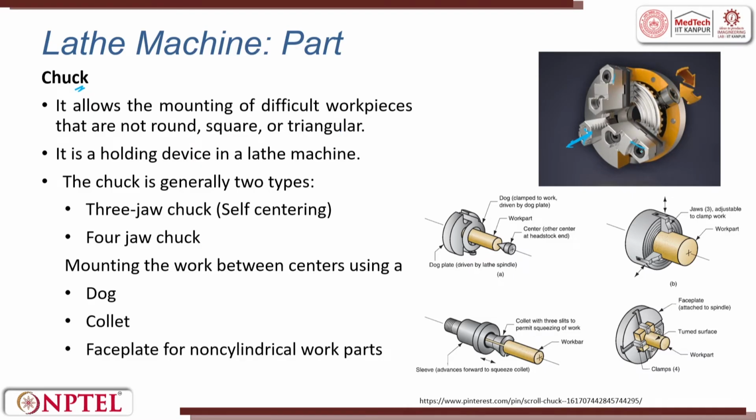The 3 jaw chuck we are talking about is predominantly used for loading cylindrical parts. Moment you have a square or a triangle non-symmetric part, then you will try to use a 4 jaw chuck. So, 4 jaw chuck is not a self-centering chuck. Okay. So, it holds the workpiece. The chucks are of 2 types. One is called 3 jaw, the other 4 jaw.